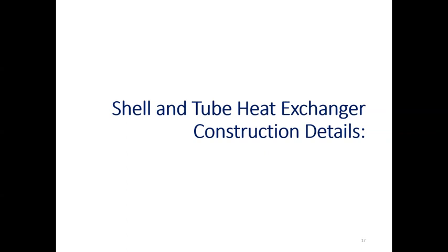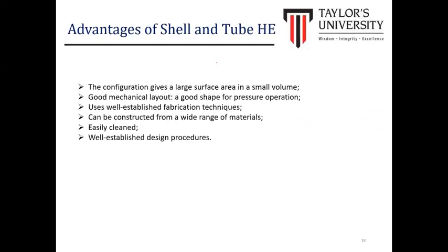Okay, we move to the shell and tube heat exchanger for the construction detail design. Advantages of shell and tube heat exchanger are we can have the configuration give a large surface area in a small volume, and it has a good mechanical layout, which is it has a good shape for pressure operation, because